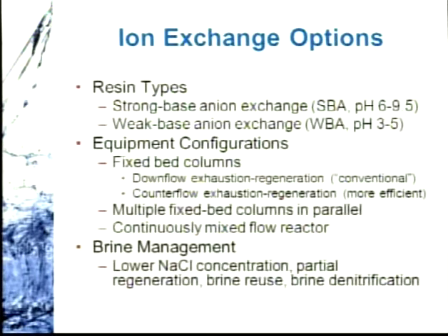The most commonly used approach is strong base anion exchange resins, or SBA, operate in a range of pH conditions, but most notably in ambient water quality conditions for typical groundwaters. It's important to qualify the fact that weak base anion exchange, which can be used for nitrate removal, although is not used for that application in full-scale applications today, has to operate at a much lower pH condition, and that is why it's not really used.